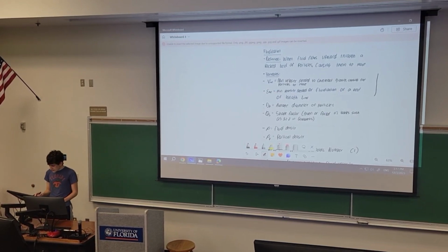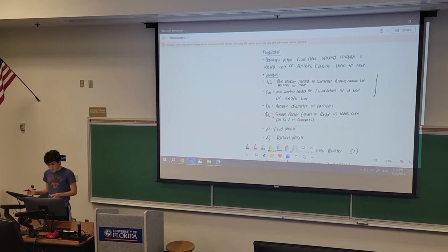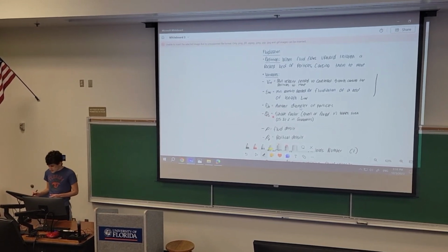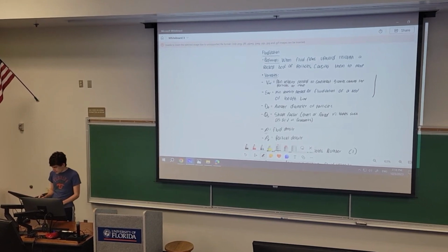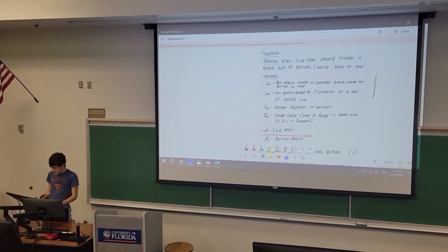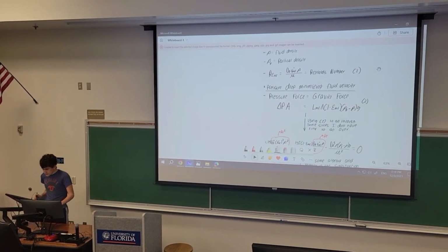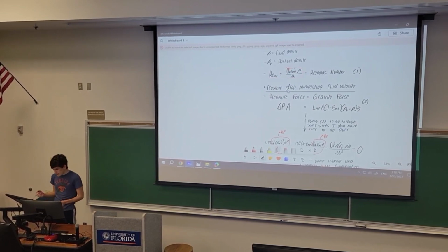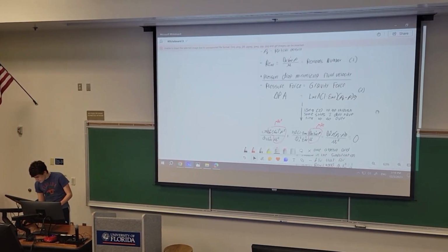And then after that we have dP, which is the average diameter of the particles, which we need to know. We also have the shape factor, which is just a factor that is given in the problem statement, or it's found in tables such as 3.1-2 in Geankoplis. And it basically just accounts for the irregularity of certain particles. We also have rho, which is just the fluid density. We have rho p, which is the particle density. We also have the Reynolds number, which has been talked about a lot, and the equations given, and it basically helps describe the flow, and it'll help you solve problems for this topic.